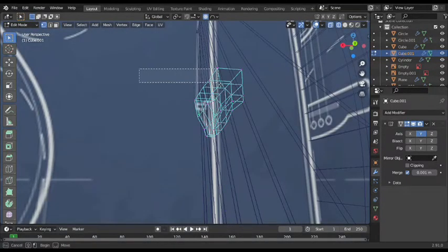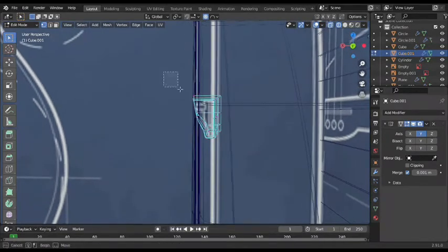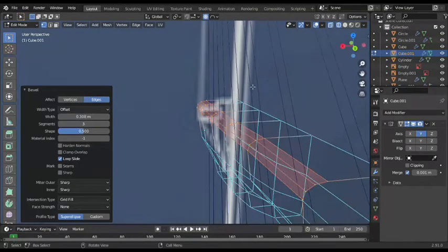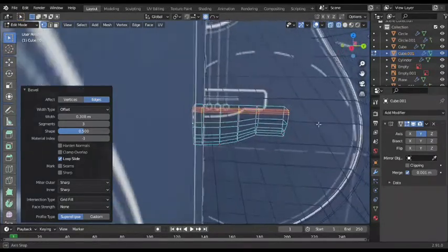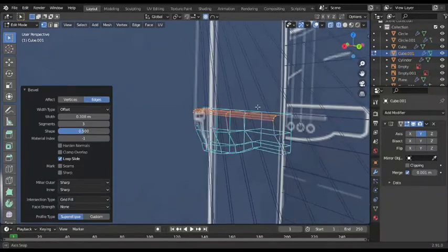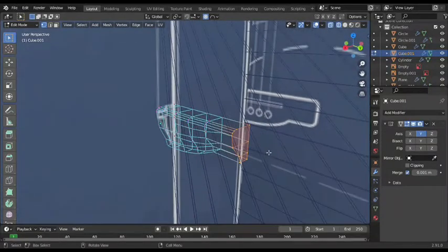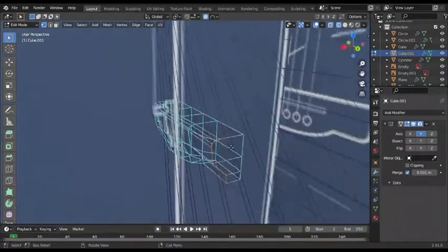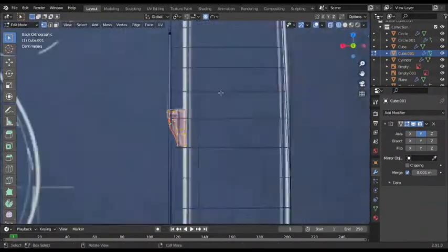Now to this entire selection, I'm gonna press Ctrl B to add in a bevel, and I'll scroll my wheel to give 3 subfaces and click. It will smoothen the edge without any need of the subdivision surface modifier. Now I'm gonna narrow this edge of it. For that, I'm gonna push this inside until I'm satisfied.